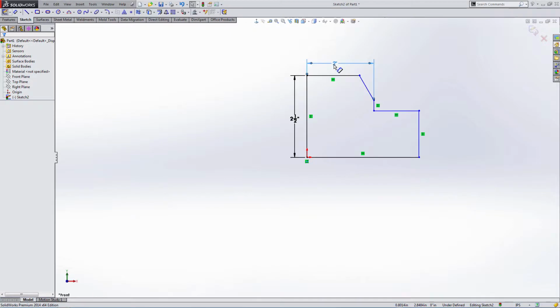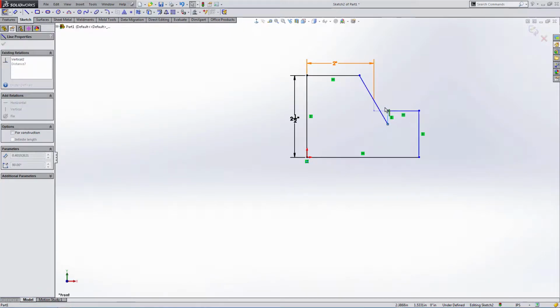The other thing is, a good time to address it now since it's showing. This is called a driven dimension. It means that it's driven by wherever the geometry is. A driving dimension is the other type, and in your setup, your driven dimensions are probably going to be a light gray. I don't like colors that are close, and so in my case, I set it nearer to a red, meaning that to me a red dimension would be something's wrong.